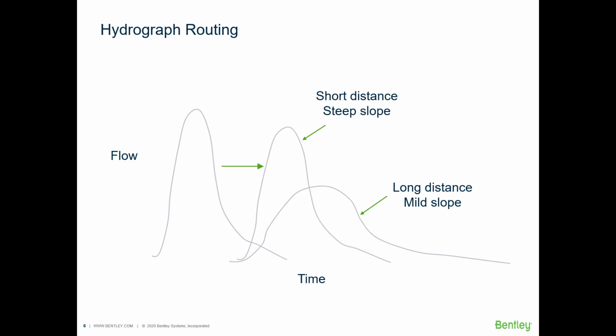But the reality is that the nature of flow in sewers is unsteady because we have things like storm events: there is no flow, but then it rains and then we see flow, and then it stops raining, no more flow. We also have things like pumps. When the pump is on, there's flow, and when it's off, there is no flow. So in real life, we know we're dealing with unsteady flows.